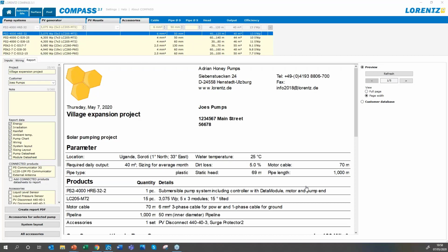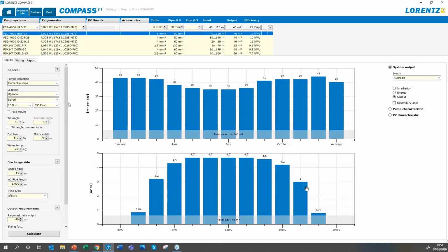This is a report that was produced when it was first drilled. And for older boreholes, it may have to be redone every few years, where a pump test is done. The pump test will work out what the safe yield of the borehole is. So the borehole might be good for 10 cubic meters per hour sustained pumping. So this is sometimes a constraint that we have to think about in our sizing.